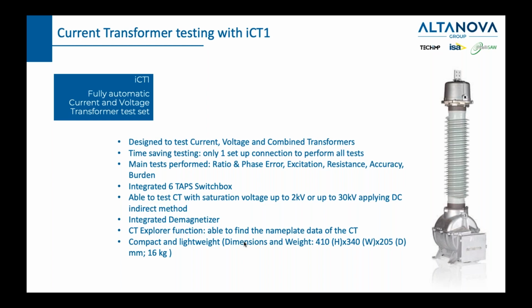Also, we have an integrated demagnetizer, which is important because, as I mentioned before, there are situations in which, especially, some differential protections did not trip or tripped wrongly because the CT was already close to its saturation point, and then the huge current came and the CT saturated. So this would be like, let us call it not mental hygiene, but demagnetization hygiene of your CT. Every time you test a CT, it's a good idea to demagnetize it.